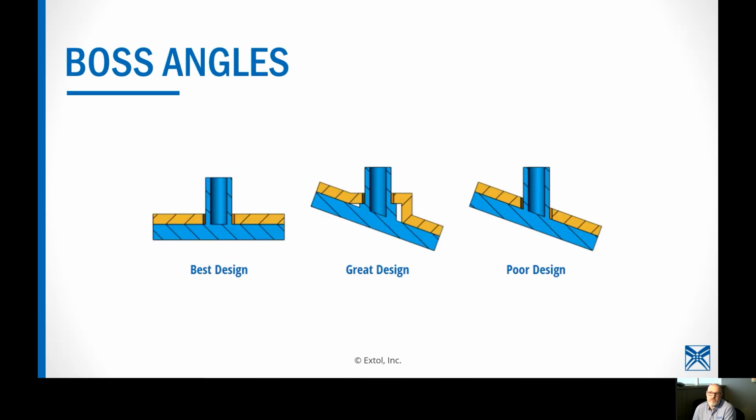Talk a little bit about angles. This is the best design for any staking technology across the board. Parts flat together, perpendicular. That's ideally what we would like to go for. We understand that you can't do that in a lot of applications, so we also would suggest putting a standoff in if you could.